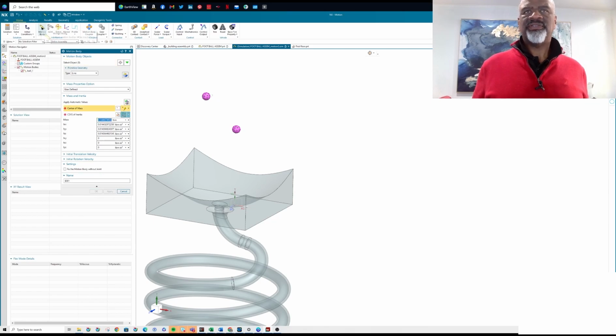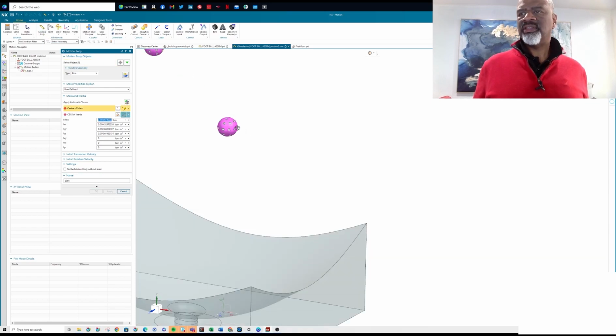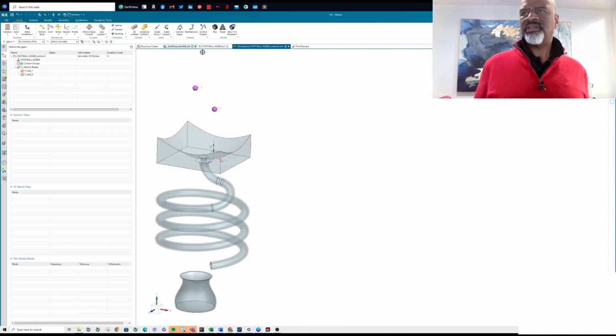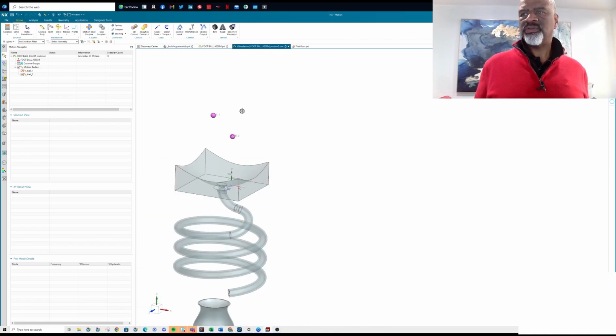And like I said, I'm going to Motion Body, and I'm selecting this one now. I have to click on Select Object, select the object, hit this little button that calculates the mass properties, and you can give it a name. Ball underscore 2. There's that. And you can see that it labels those things.